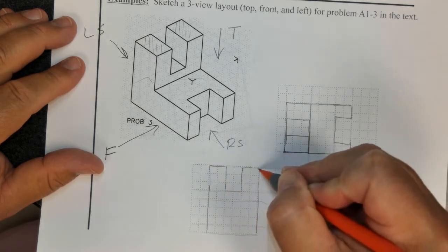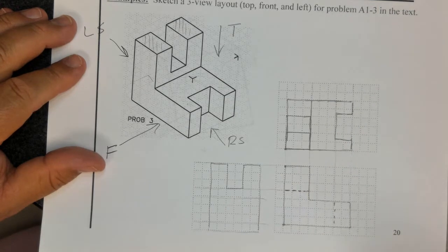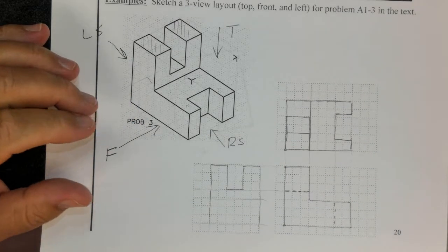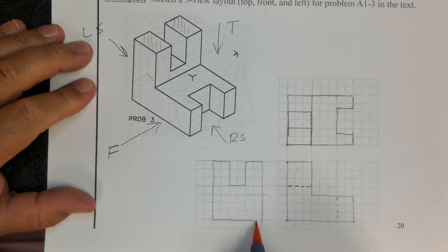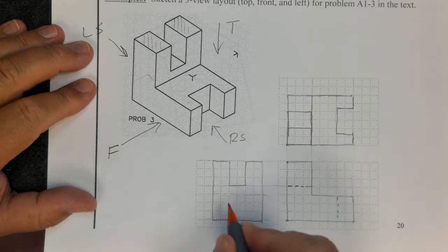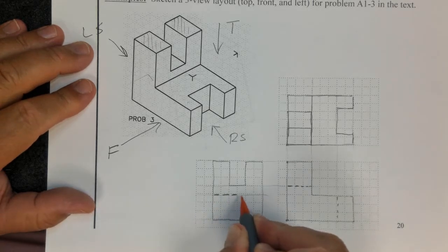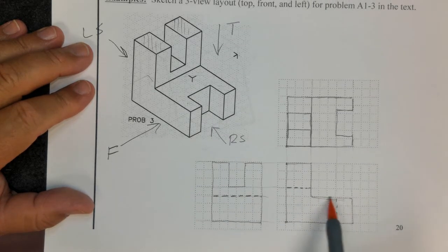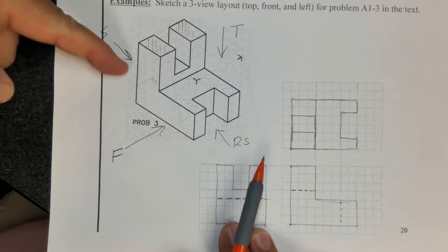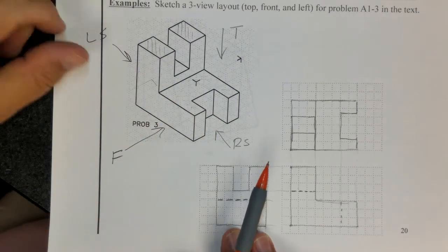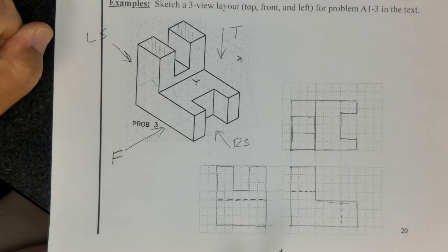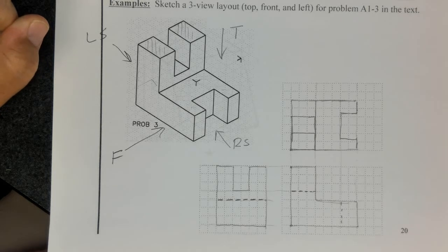Okay. And then, by the way, I came down just a little too far here. I'm sorry. Let me erase that line. Oops. Came down just a little too far. So it should actually be right there. Sorry about that. This is going to be a hidden line because we cannot see this surface right here looking from this direction. We cannot see this surface. Okay, remember the line of sight is perpendicular to that surface. So this is what this view would look like, okay, or this block would look like.